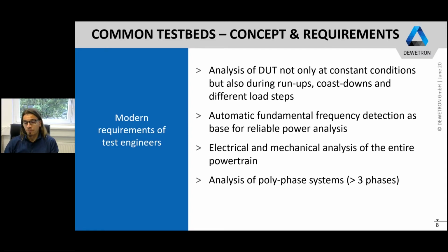And for being able to always refer to the raw data in the case that the power parameters have a strange trend in the time domain, you always want to analyze the root cause, and therefore the power analyzer needs a possibility to gaplessly store the raw data during the measurement and during the power determination.